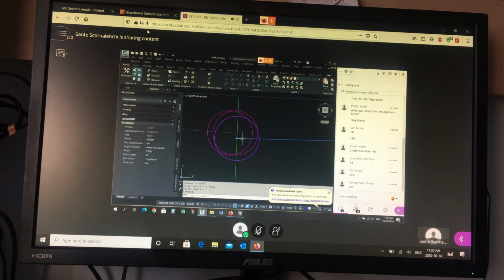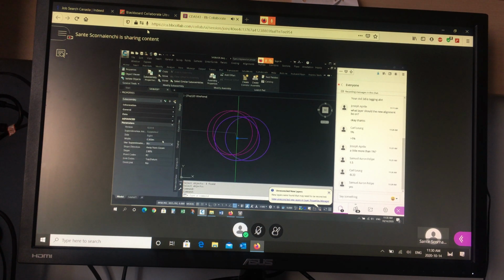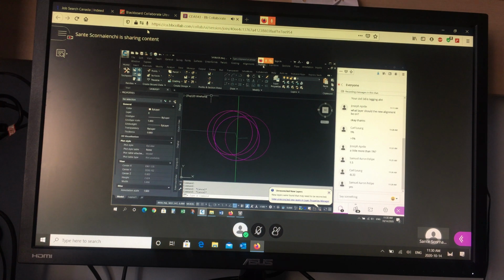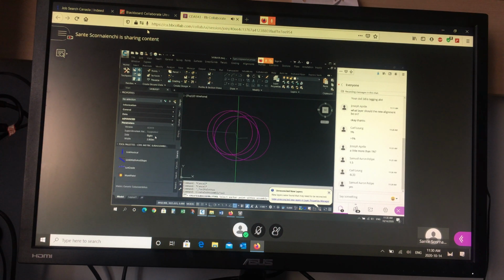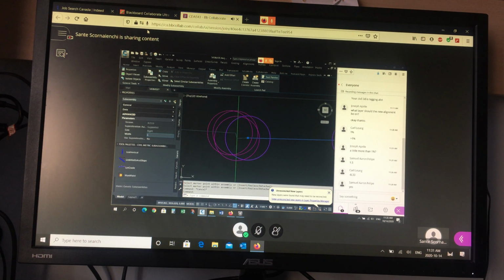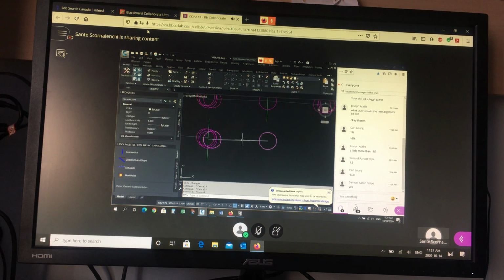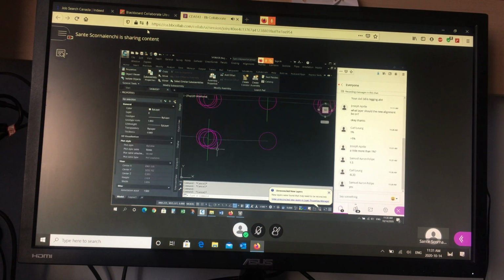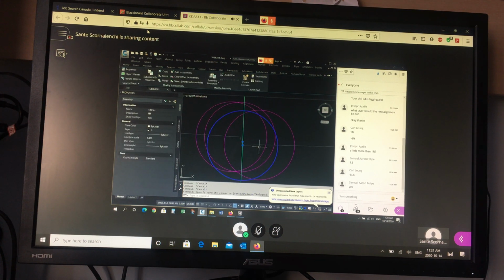Should be there. This piece is the gutter, 0.3, and it should have a positive slope of 8.3333. And now I'm missing the pavement on this side, so I'll add another piece. Profile, create by assembly, tool palette. And I'm going to create a link with slope on the right side. And this is the piece that has to be 3.95 with a positive 2% slope. See, the reference point is now the gutter, not the edge of asphalt.